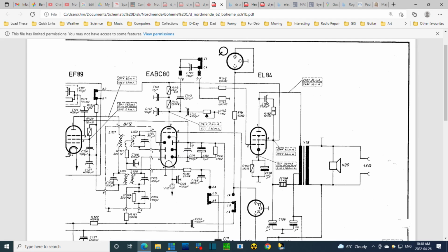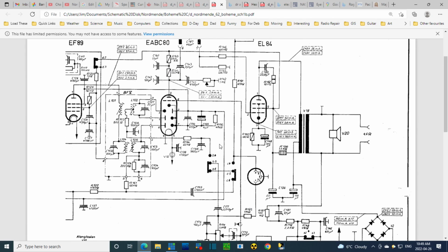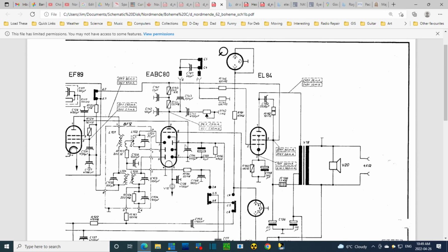Just double checking a couple things here. Let's say, okay, because of this 4 microfarad capacitor, I think this is the FM side of things. It's getting its signal out of here. Yes, definitely FM. This part is apparently working okay in terms of producing an AVC voltage, which is being cast through the radio apparently appropriately. The other two must be for the AM bands.